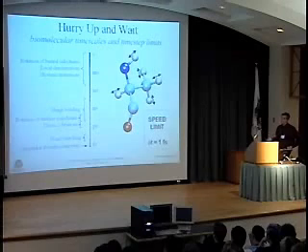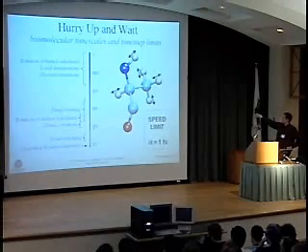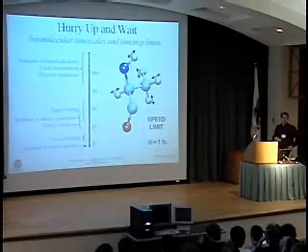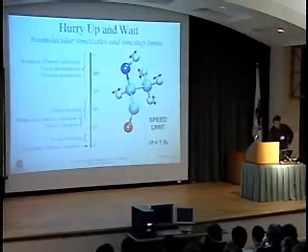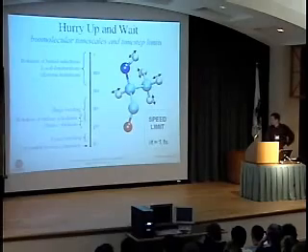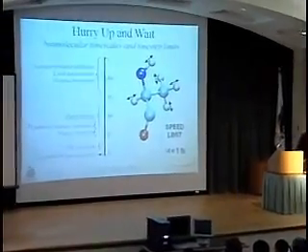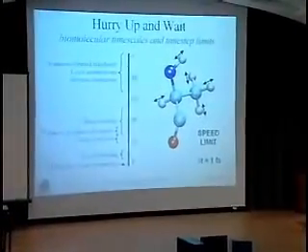And because of that, we're faced with a time step of 1 femtosecond. And that's actually constrained by the vibrations of hydrogen atoms, because those are the lightest atoms in the system. So we're stuck with a 1 femtosecond time step, and it takes 1 million time steps even to simulate a nanosecond. So that can take a while.